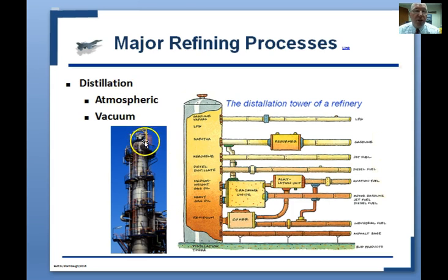So again, this is a picture of the distillation tower, which is the first stop in the refinery process. I want you to be basically familiar with how this works. You can go back and rewatch the video, but remember they heat down here and then they use a lot of natural physics. And if you understand the physical properties, this becomes easier. What this means is they heat it down here, and as it rises, it naturally cools. The heavier molecules condense sooner in the bubble caps and are removed. The lighter stuff goes to the top.